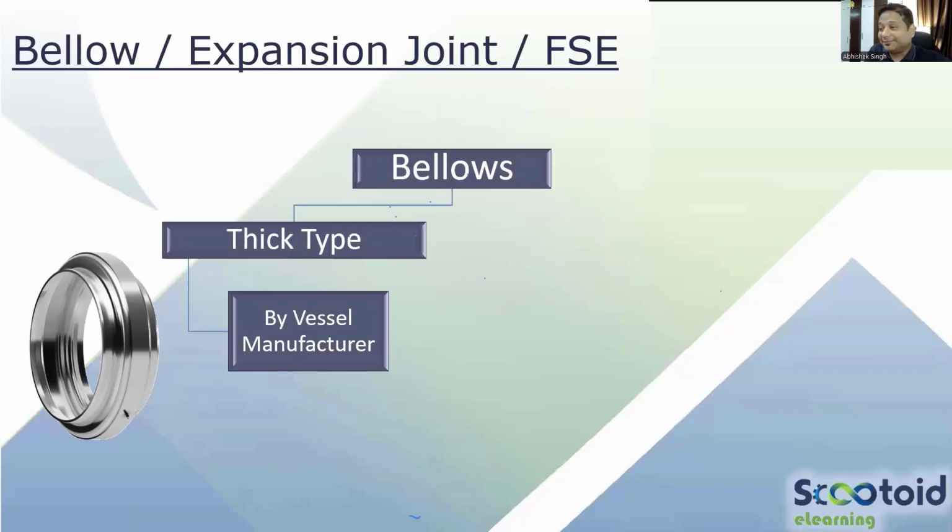Now the question, somebody asked why that design by rule method was removed. So the reason was that it was not giving accurate stresses. The stiffness calculation done by that method was not accurate. It was giving a very high stiffness, okay, compared to what you get from the dimensions.